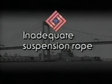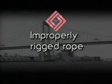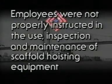It had inadequate suspension ropes. The ropes were improperly rigged. The hoisting machine did not have a secondary emergency brake. And finally, the employees were not properly instructed in the use, inspection, and maintenance of scaffold hoisting equipment. The employer has contested these allegations, but the fact is, Robert Smith is dead.